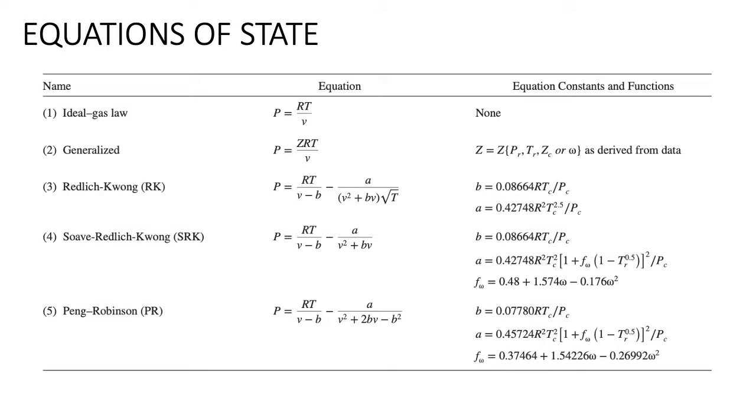First, I'd like to show you back a few equation of state models that we normally use for our thermodynamics calculation. So in this equation of state, basically showing us a relationship between molar volume, temperature, and pressure, which is shown in the PVT equation of state. So there are many equations that have been proposed, of course, and the simplest one is the ideal gas law.